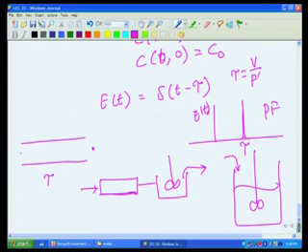The fluid is coming in, and for some amount of time there is very little mixing in this region, let us say. So, it behaves like a plug flow. So, I show it as a plug flow, and then for the remaining portion of the reactor there is uniform mixing. So, it behaves like a stirred tank reactor. So, my original single reactor is now, let us say, a combination of these two reactors.